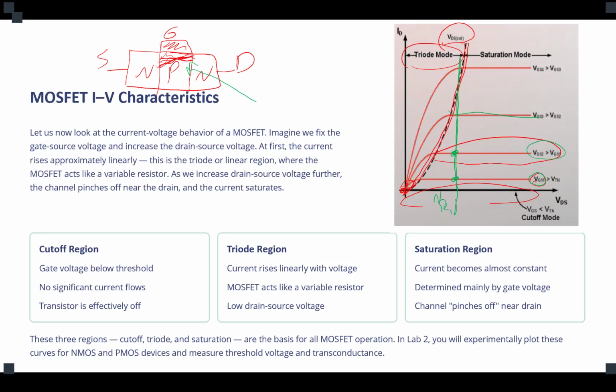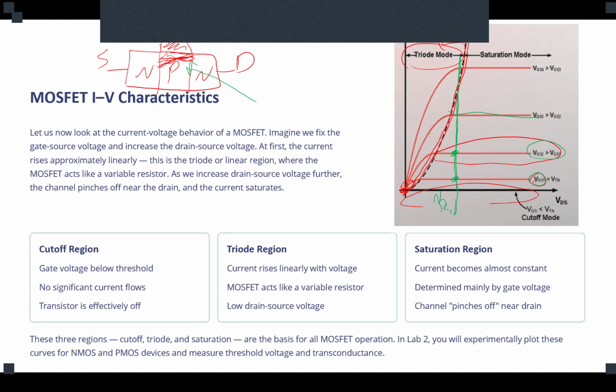We normally use the MOSFET as a switch, so it's turn on and turn off. We don't use it as an amplifier. So it's better to have a constant current. Either it's on and conducts a certain amount of current, or it's off and does not conduct any current. So this is one reason, regarding the application of the MOSFET, that we want to keep the MOSFET in saturation.